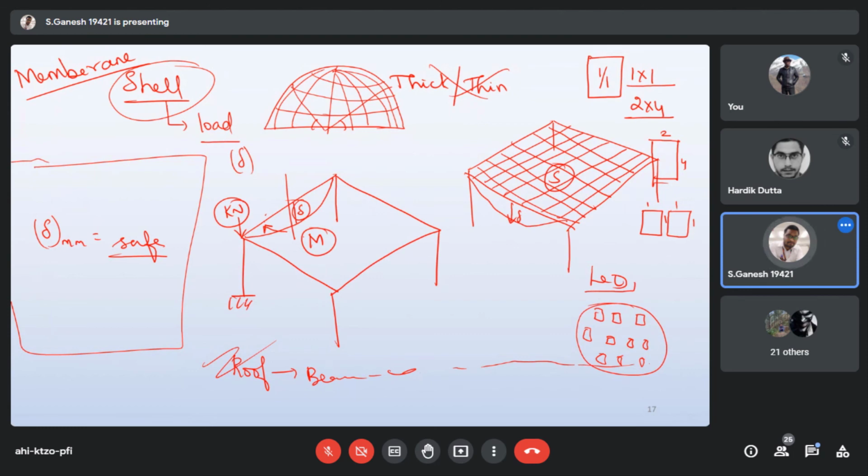Okay, Yuvraj: while using the floor load command, can we assign the self load of the slab in the floor load command? Yes. When you use the floor load command, the self weight of the slab is assigned automatically. Wherever the self weight -1 you are giving, it is already taken care of. Or the day 2 load calculation I explained to you, right? You can take that calculation sheet. How you calculated the self weight part, 0.15 into 25. You are already calculating the weight with respect to density, and you are incorporating those load values. So it will be taken care of by the software when it is running.